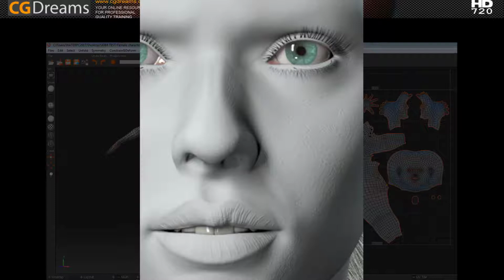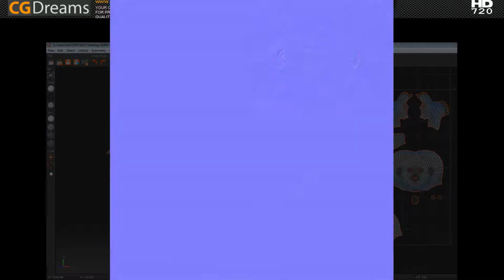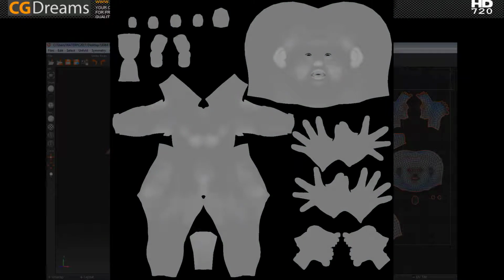Again, these maps can be made while the UV map is relied on, and these are called bump and normal maps. We can also control many aspects of the material, such as how glossy a surface is, where the hair can grow off an object if your 3D application supports this, as well as many other control maps.